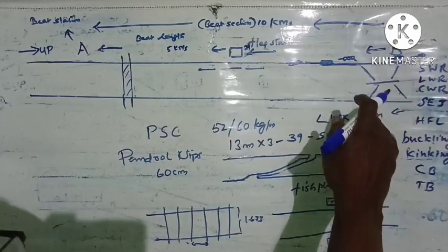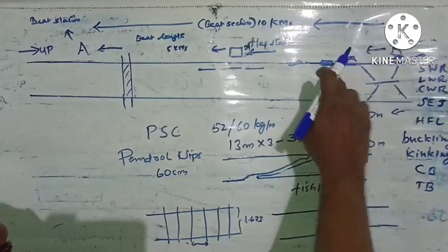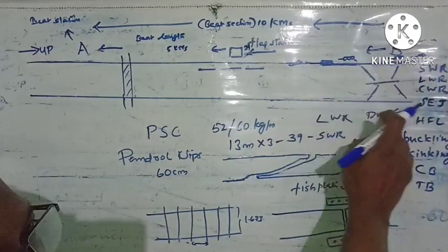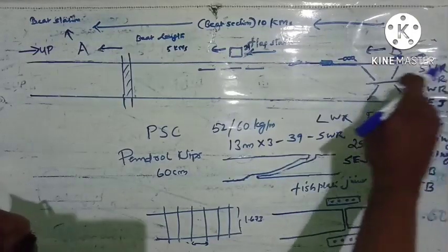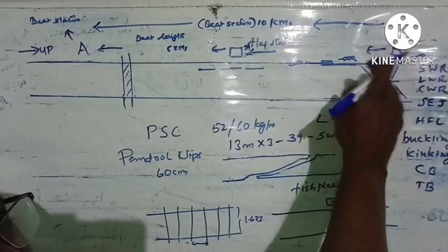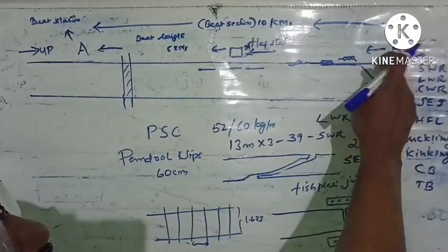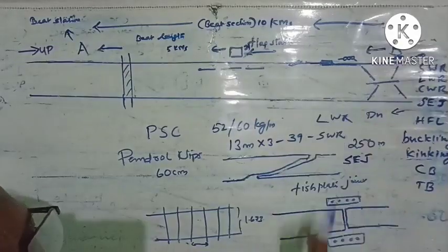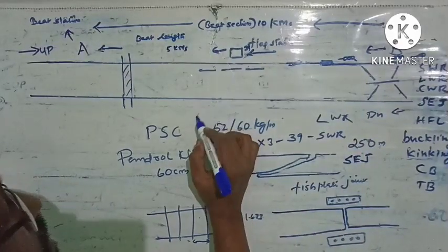are interlocked, and there will be track circuiting. Here the electric connection is through the track. So if the track goes continuously throughout, then it is not possible to have separate track circuited portions. So here we have several joints.